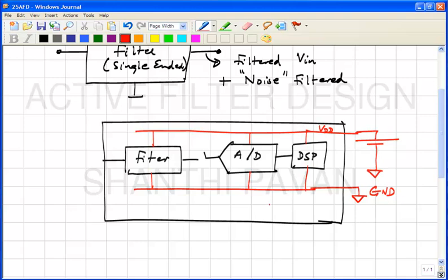All right. So this is the chip. Now the DSP is running a whole bunch of gates, right? And we'll probably be needing a master clock from outside, which goes to the DSP, also to the A to D converter, because the A to D converter needs to figure out when to sample. And perhaps the clock is not directly sent out, perhaps you want to multiply up the clock frequency by some number and then send it to different blocks, but this should serve to illustrate the point.